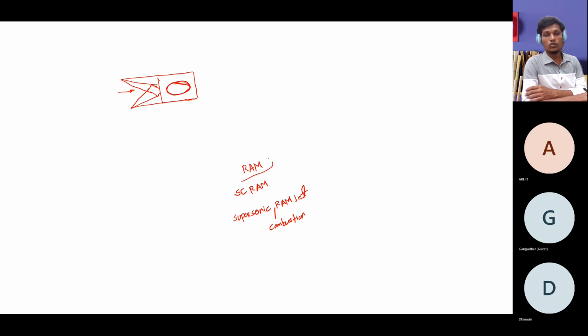So in your ramjet, you combust your fuel by reducing the velocity to subsonic levels using the shock waves and converging area. But in the scramjet, you are maintaining your velocity, or you decrease your velocity but it still remains at supersonic levels, and at supersonic velocity itself you are doing the combustion. So it is a highly difficult task to design these kinds of engines, but research is going on, and some successful designs are available. That's why we call it a supersonic ramjet, or scramjet engine, or the ramjet engine. Both use the technique of the convergent divergent section.